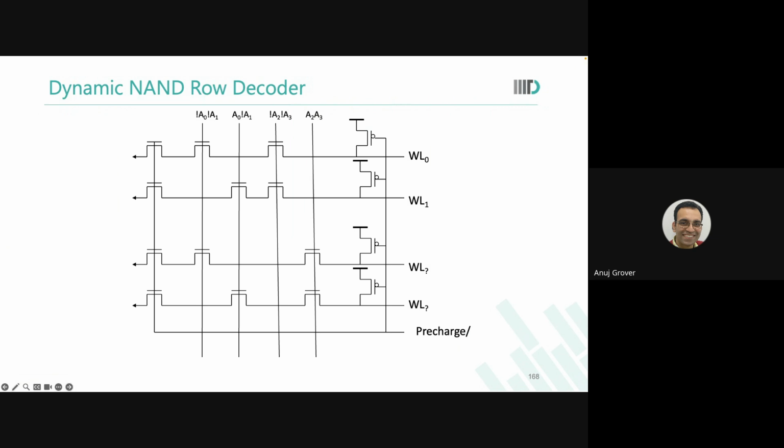If you were to precharge both the sense amplifier and bit lines at the same time, after the sense amplifier has acted, my memory reset would happen very, very slowly. But if I separate the two precharges, I can start to precharge the bit line much earlier.